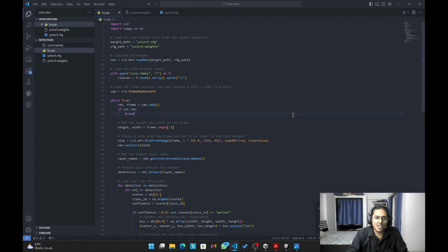As you saw the demonstration of human detection, we are also working on a model that can detect objects such as buildings, cars and trees, all these different types of objects which a drone can capture from a height of 50 to 100 meters. Also, if our human detection fails in some area because some obstacles cover the person, then we are also trying to use a heat system, so it can capture human heat and generate an alarm if it sees a human being stuck in the disaster area.